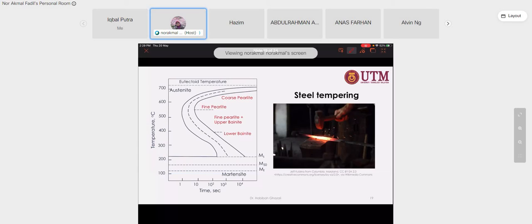Okay, to maintain the sharpness, the hardness property is required, because it doesn't change plastically upon impact load. Okay, meaning it doesn't easily become blunt when we apply impact load. It doesn't change its sharpness shape. Okay, let's say this is the knife. Okay, the sharpness at this blade. Alright, so it must maintain a certain degree of hardness, so that it won't easily deform plastically.